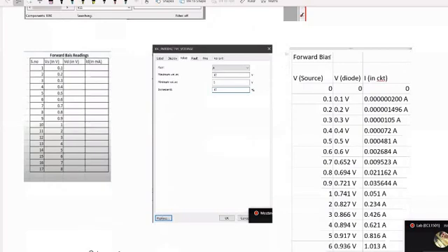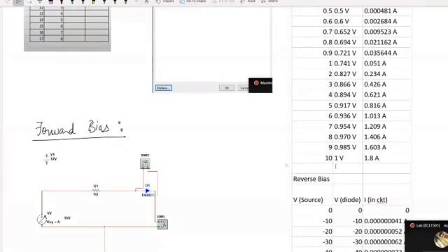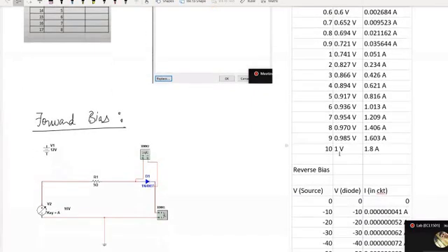Last time, for the previous group, I had entered these values manually, so it took a lot of time. But for you, I searched on the net. It's available quite easily. You could also search on the net. This DC sweep plotting gives us a convenient way to plot this curve on Excel without going into manual entry of data. You could also change the minimum and maximum input voltage one by one, and measure the voltages according to these settings.